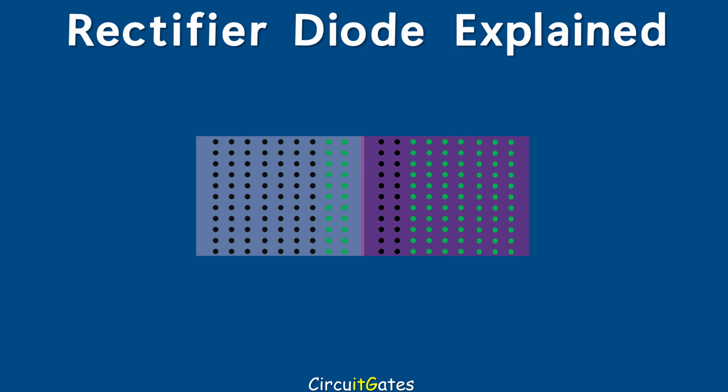As electrons cross the junction, the n-type material loses electrons, resulting in a layer of positive charges or holes near the junction in the n-type material. Since the p-type material is neutral, it has an equal number of electrons and protons. The electrons that cross the junction from the n-type material will cause an excess of electrons in the p-type material, resulting in the creation of a layer of negative charges or free electrons near the junction.